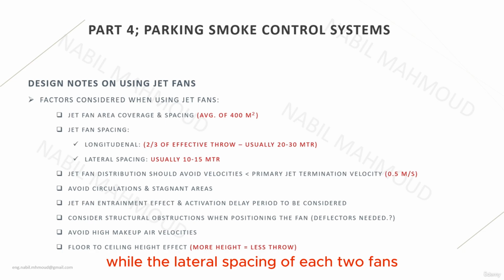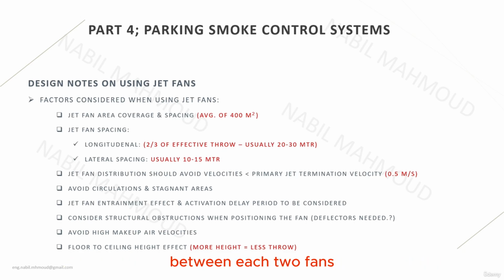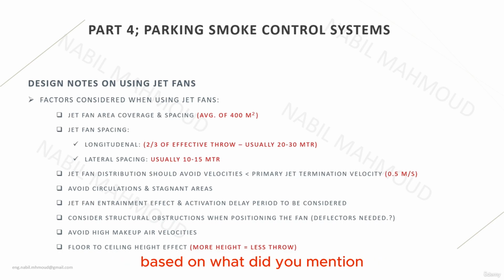The lateral spacing of each two fans usually ranges between 10 up to 15 meters, which means you will put a separation distance between each two fans of approximately 10 to 15 meters. Okay. So this also leads us to a very important piece of information. Based on what did I mention these spacing values?